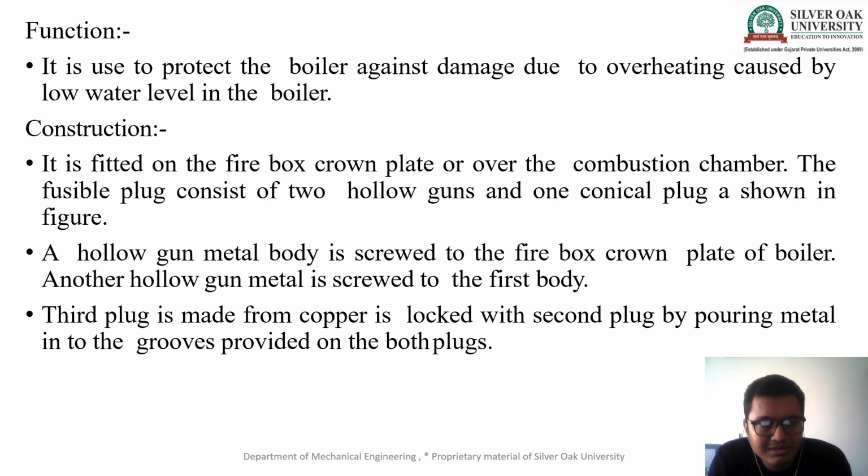Now the function: it is used to protect the boiler against damage due to overheating caused by the low water level inside the boiler. It is fitted on the firebox, or we can consider the combustion chamber or furnace. The fusible plug consists of two hollow gun metal pieces and one conical plug, as shown in the figure.